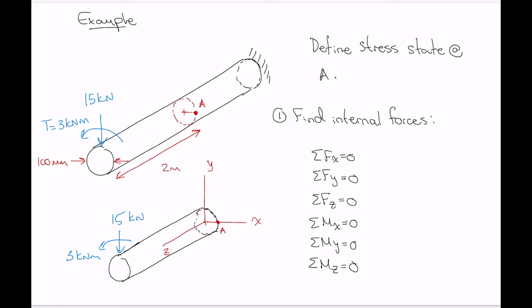And that's going to throw everything off entirely. So the z-axis is the longitudinal axis of this object, so we shouldn't be doing the sum of the moments about z. We should be doing the sum of the torques about the z-axis. Has to be equal to 0.